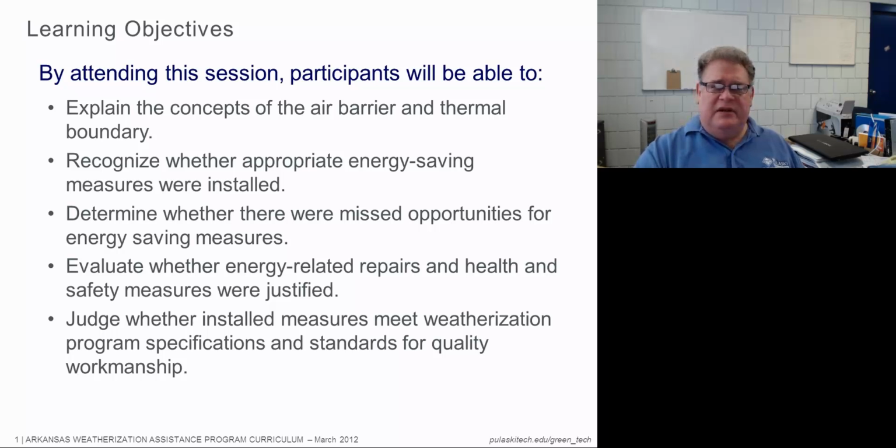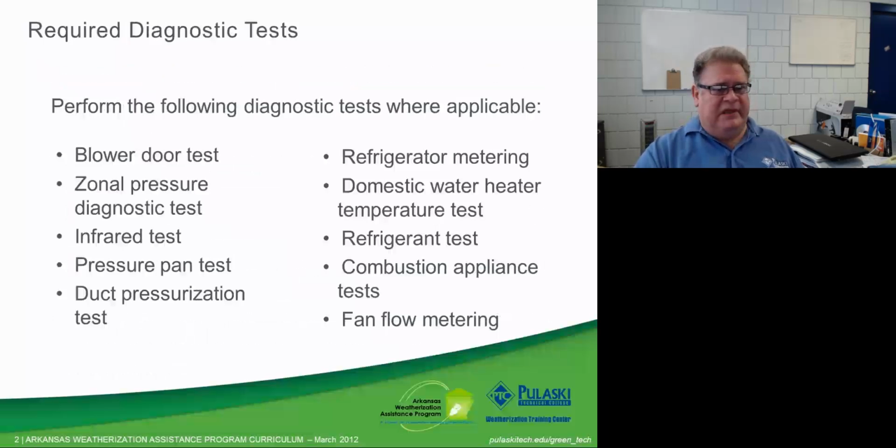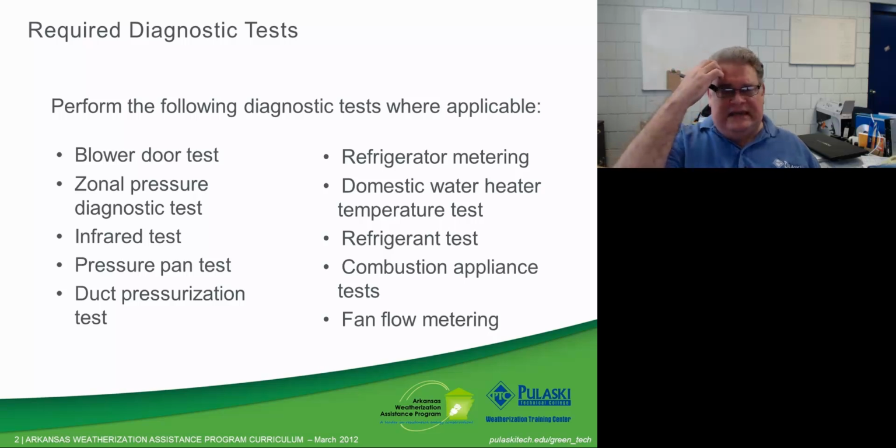The other thing that you need to be able to judge is workmanship. So what we want to see is being done when we go out and take a look, where applicable, we want to make sure that we run a blower door test, we do zonal diagnostic tests, we run infrared if the conditions are correct. We want to do an infrared inspection. We want to run a pressure pan test, and if our program is doing it, then we want to run duct pressurization tests. We want to meter the refrigerator.